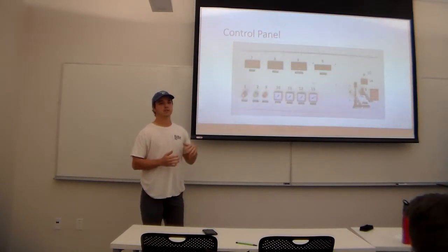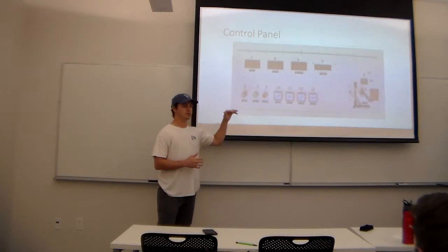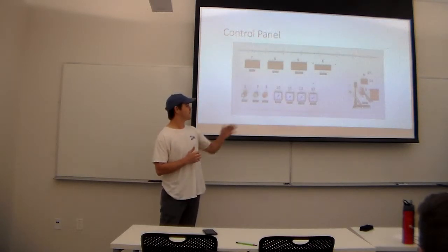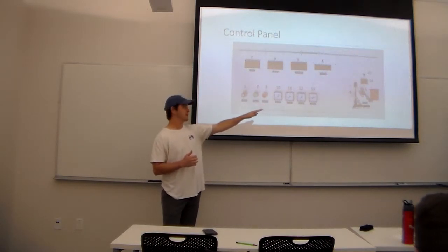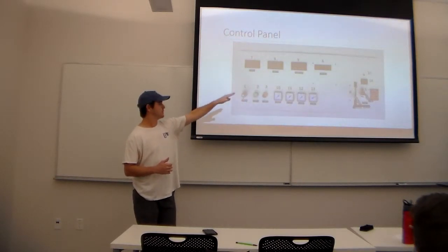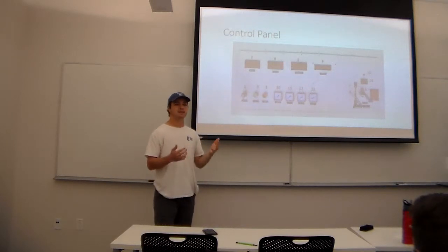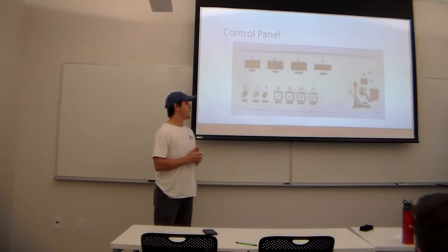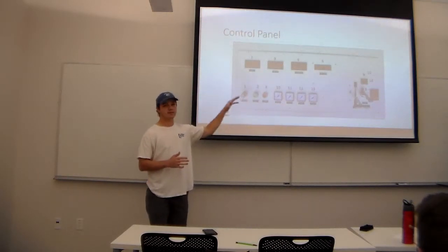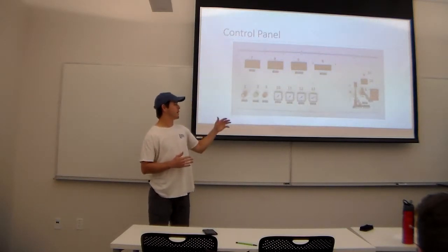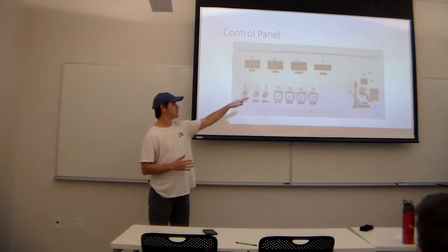So if you want to generate more RPM on the turbine, you pull it up. For the first test, we just tested the main power turbine by leaving the 5 switch down on the free turbine and pulling up the thrust on the 4 turbine, the thrust nozzle, which lets us see the RPM of the power turbine. And then for the second test, as we turn on the thrust of the power turbine, we also regulate the free turbine by pulling up those switches on 4 and 5.